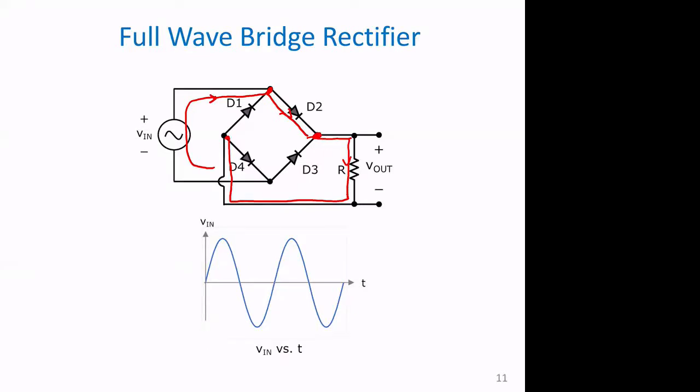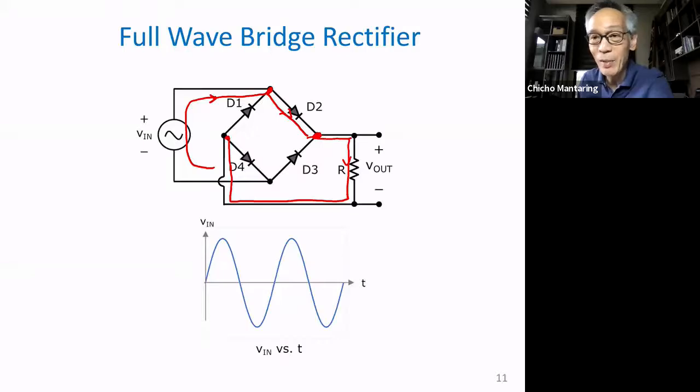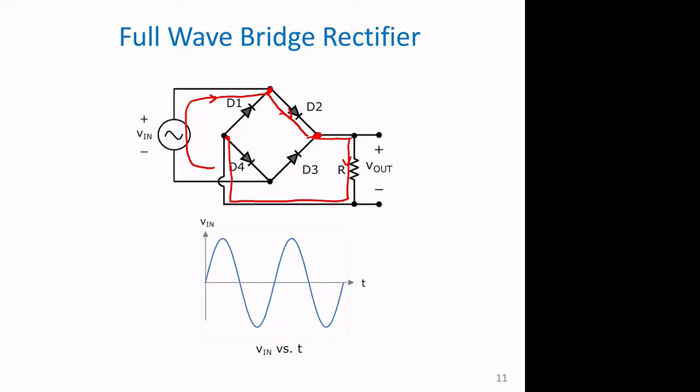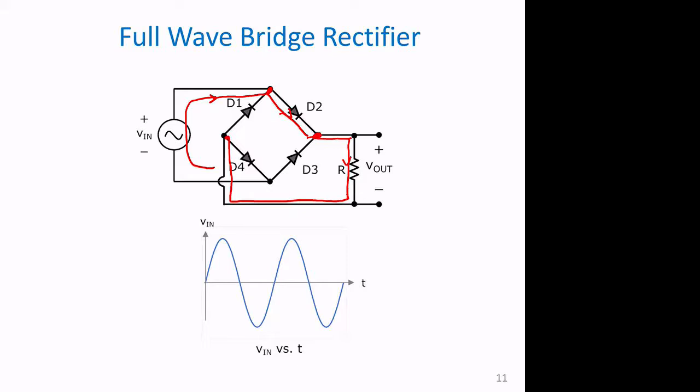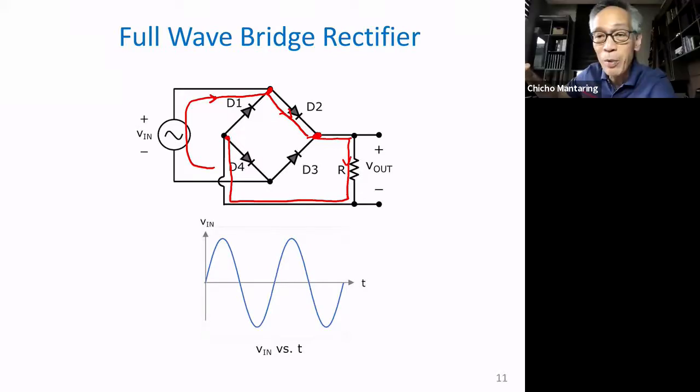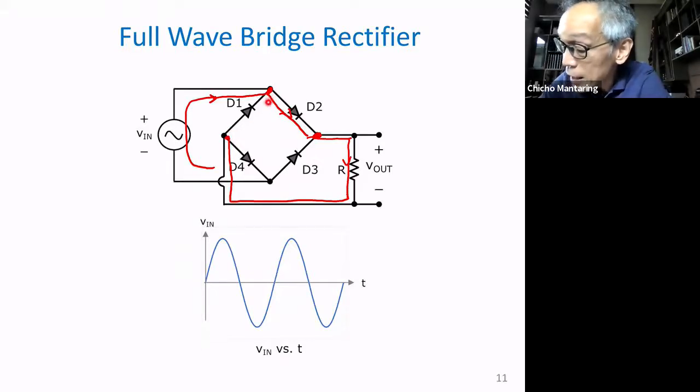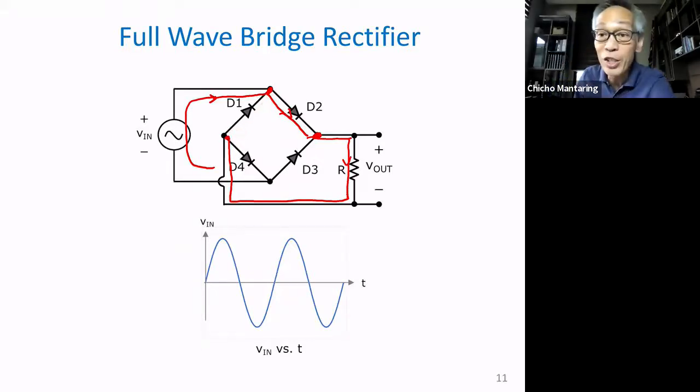Can I hear someone who hasn't talked? No, sir. Explain why. The voltage at the cathode is higher compared to the anode. That's right. The direction of current flow is from higher potential to lower potential. If the current came from there, that potential is higher. So the current came from here, it's already here; if it goes back there, it would need additional energy.